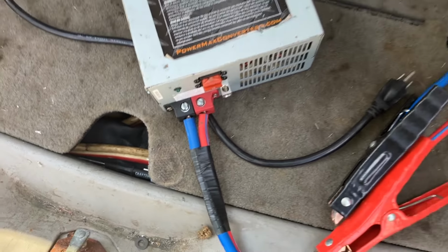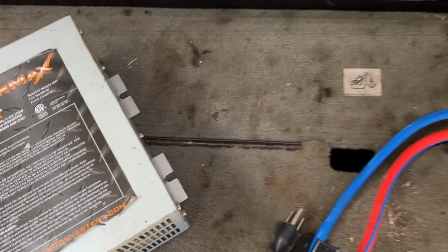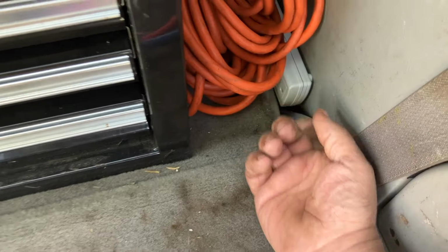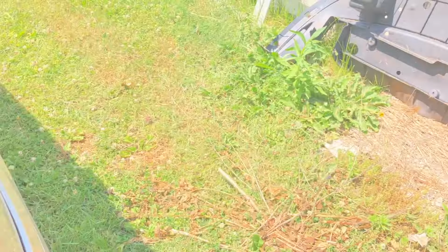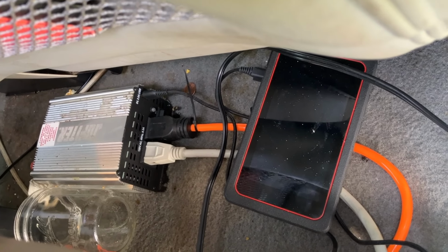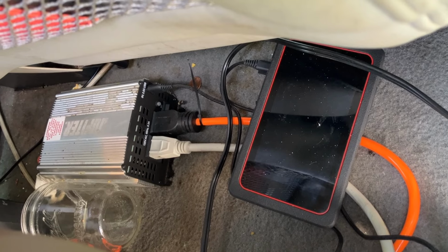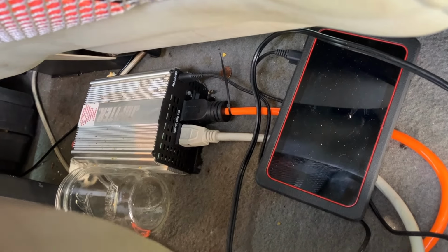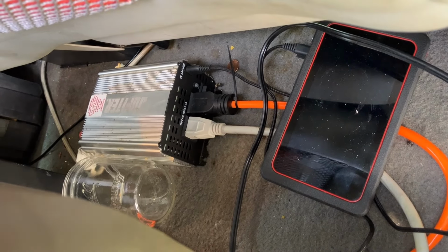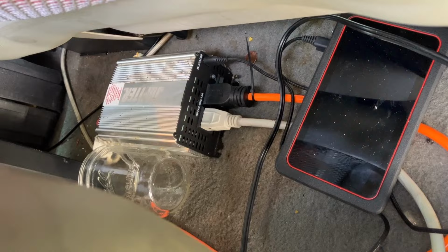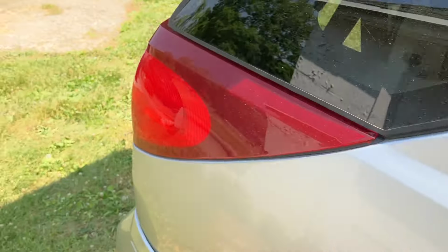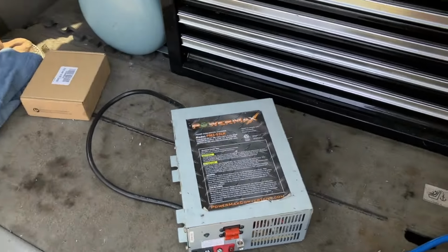And so I'll plug this in. Now, if I'm at a house or something where I can take my extension cords and plug in, I'll do that. If not, I will plug in to my surge protector down here, which is hooked to my power inverter. And I'll have to leave my car running when I do this too, to make sure it gets enough voltage. But I have a little 1000 watt inverter down there, and that comes out to this surge protector, and that extension cord runs back to my other surge protector. So I turn everything else off, and that draws about 750 to 800 watts at full power.